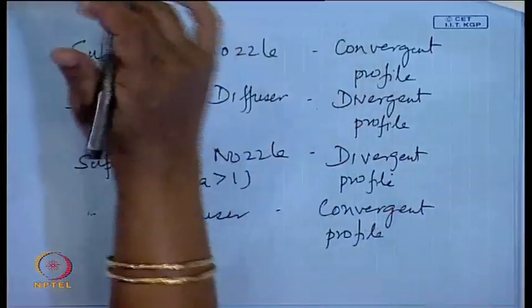Okay. So, this is something very important that you should be noting, that the behavior of compressible flows is not consistent over the entire range of Mach number. One type of flow characteristics is exhibited for Mach number less than 1 or under subsonic conditions, and just the reverse type of phenomenon is observed for supersonic conditions. And that explains why Mach number equal to 1 is so very important. For Mach number equal to 1, it is usually termed the choked flow condition, or the condition of choking.